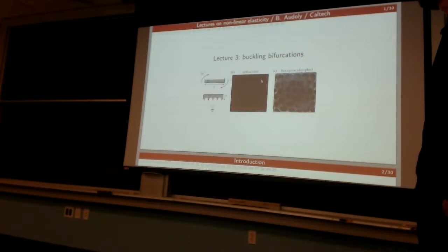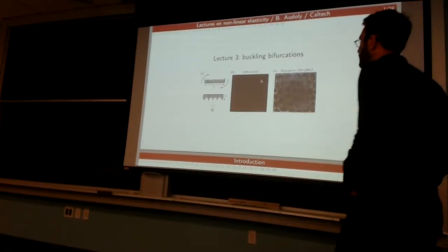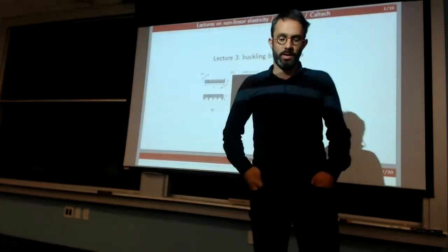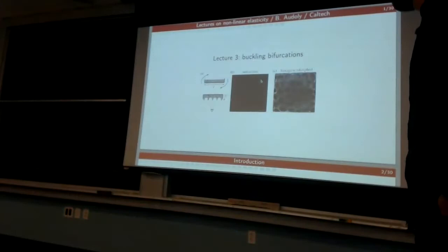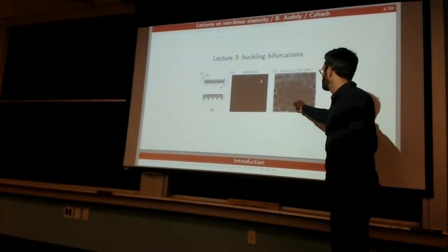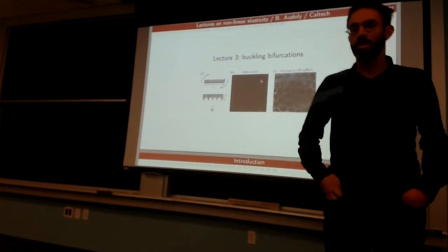So it's a nice experiment because it's quite simple. There are no big questions about modeling. You can actually model this as even a neo-Hookean material, which usually is not a very good model, but is enough to capture the instability. So it's a finite elasticity problem, if you want.